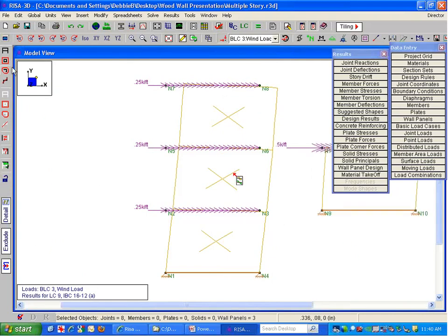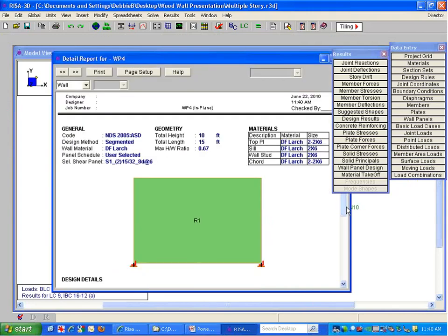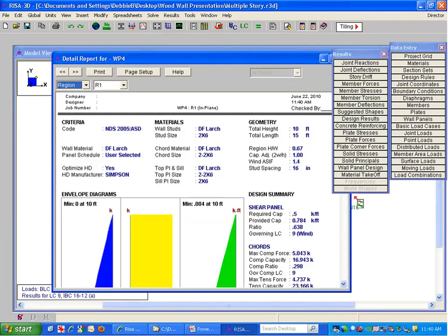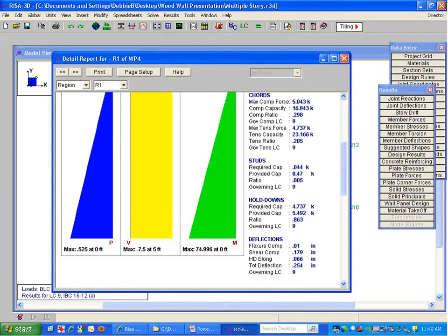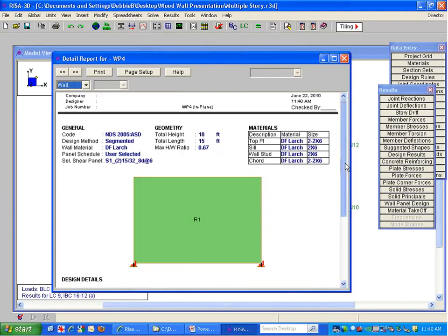to verify that if I did have that hold down elongation value, which this one has, it has the exact same shear values there in the region. I can see I'm using exactly the same 0.75 shear. My total deflection is 0.25 in the wall on the right side.